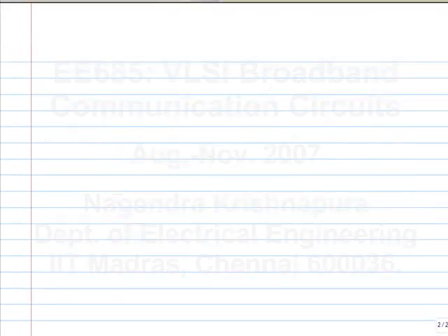So, the first thing is once we recognize that we are talking about 2 different frequencies for this trade-off, 2 different frequencies at which the values of KPD and KVCO are relevant for lock range and for reference feed through. We can make it high at low frequencies where we want it to be high and low at high frequencies. So that means that the phase detector itself or something else in the loop should behave like a low pass filter, which makes the phase detector have a large gain at DC and small gain at high frequencies.